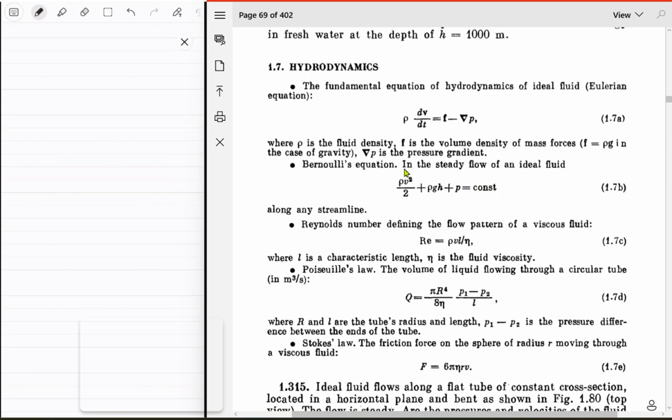Right. So this is done using energy conservation. That's how you get the derivation of this thing. But then energy conservation is along only one streamline, and that's why they are saying this equation is true only along one streamline, right? So along any streamline, you have this equation. But if you go from one streamline to some other streamline, you might not have this happening because the constants for those two streamlines might be different.